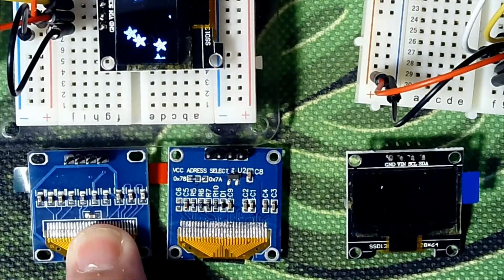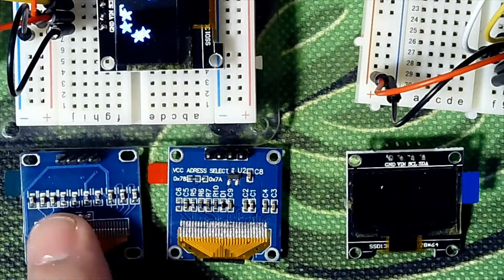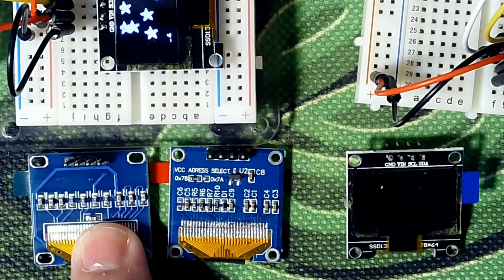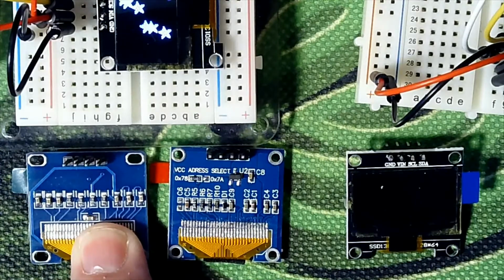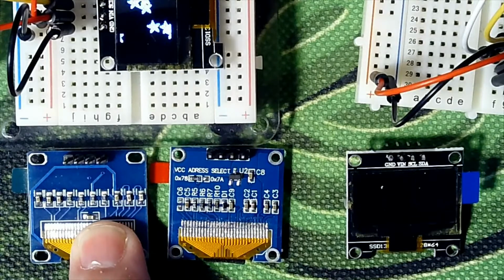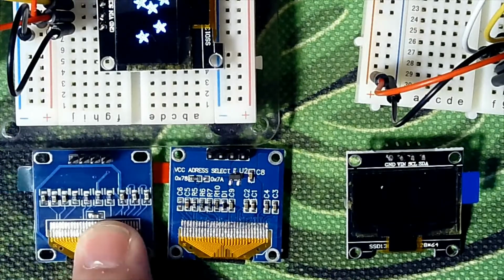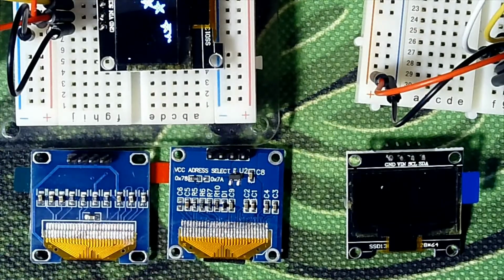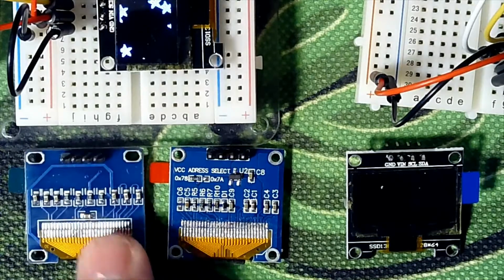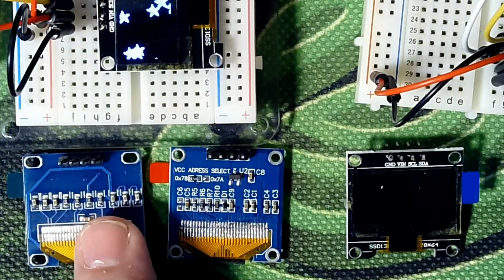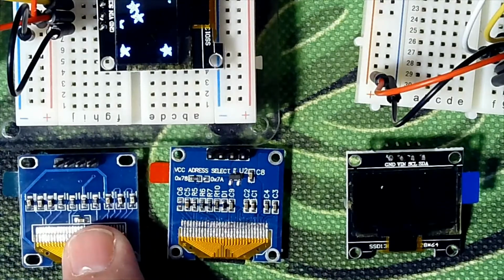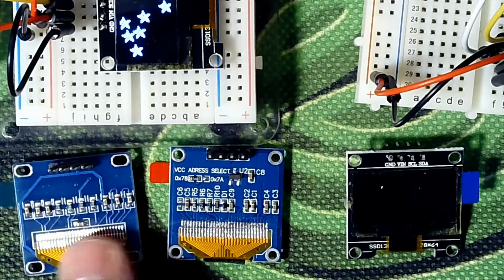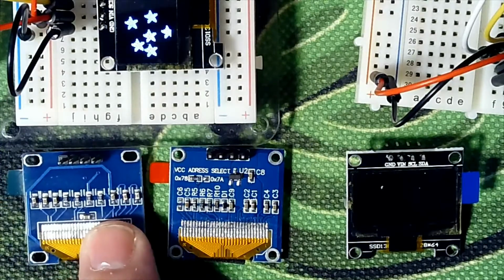This one, when I scan it, there is no address. There's no way to change an address. There's no jumpers to change. Usually these are selectable. I'm not able to get this one to work. So I bought these quite a while back, put them in my stock, and eventually went to go use them, and I couldn't get them to work. And I played around and played around and played around, and I tried using the default addresses of 0x78. Then I tried 0x3C, and nothing seemed to work. I tried scanning them, I couldn't read them.